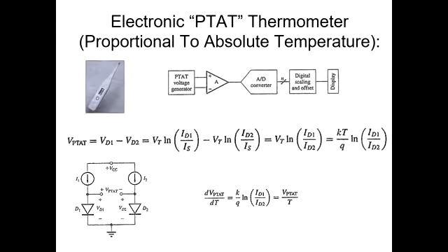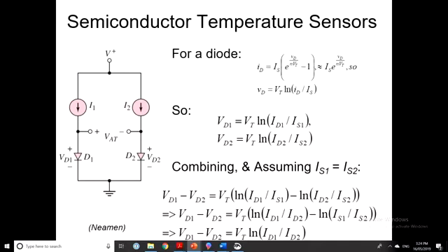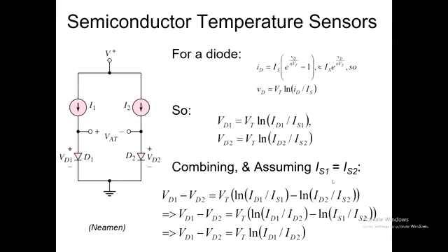Mainly discussing the sensitivity of diode junctions, semiconductor junctions, to temperature in the first instance, and also illumination. So here's an example of a clinical thermometer, and I left you with these couple of extra slides to work through to make sure you understand how that works, how we can cancel out the very tricky and awkward bias that's very temperature dependent.